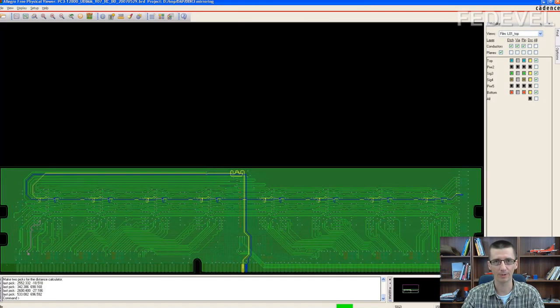You already know what is important for the T-branch topology, but what is important for flyby topology? Read the design guide. But this is basically what you will find out. I'm going to show you. For the flyby topology, it's important that you route signal from processor or FPGA to the first memory chips in some kind of tolerance.